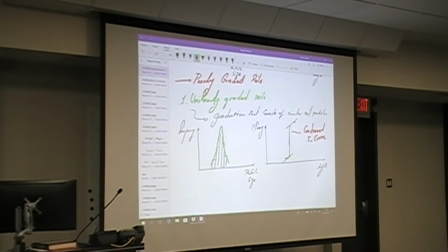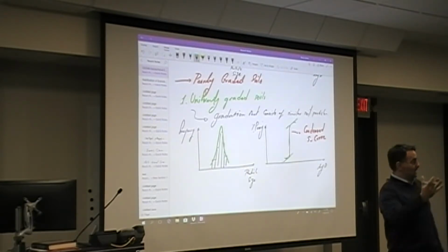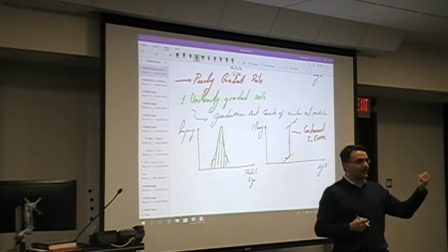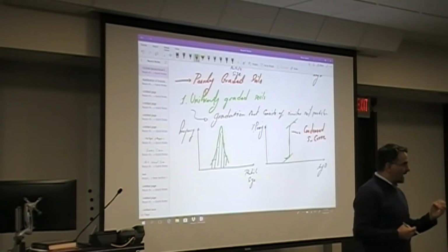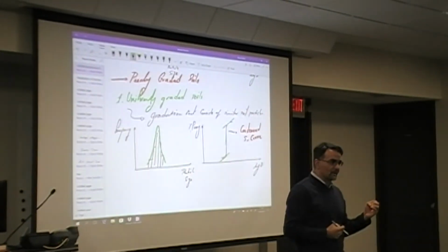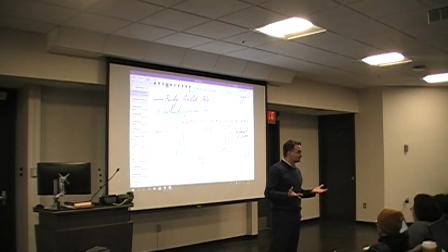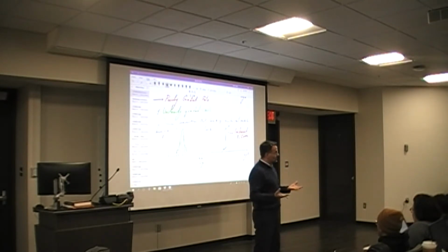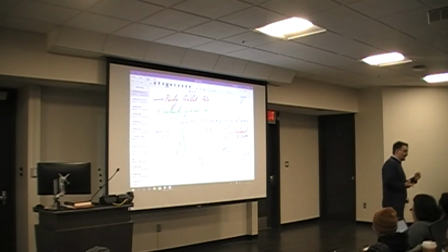Are you familiar with isolated voids? That's like one random hole. Hopefully not that big, huge gaps, right? What's the purpose of air entrainers that we have in concrete? Allow for expansion in cold weather. Yes, and it also creates bubbles. Those bubbles are small, and they act as quote-unquote aggregates for you. They also reduce the weight of the structure, so the total weight is going to be lower. You're going to have small voids in there. They're not interconnected.